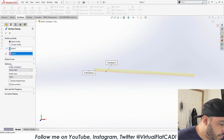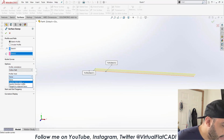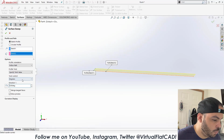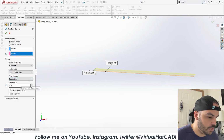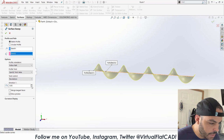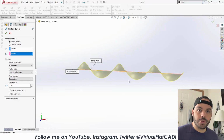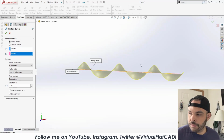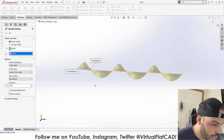It's not looking like a helix at all, but that is perfectly okay. Because to fix that, we'll go to our options, and you'll notice we have this value for profile twist. In that, I'm gonna specify a twist value, and instead of degrees or radians, we're gonna go for revolutions. I might have to adjust this later, but you don't want the coils to be too tight, because eventually we're gonna use this to actually drive the shape of our flag waving. So I'm gonna start with 3, I might adjust that later, we'll see.